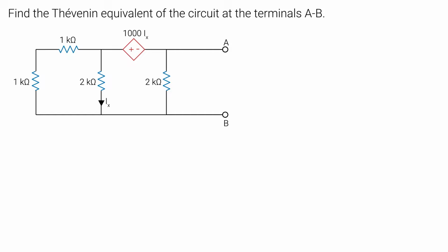Because this circuit only has a single dependent voltage source, there is no way for us to figure out a VOC or RTH since there is actually no current flow in the circuit. But we do need a voltage between points A and B. So instead, what we do is attach a 1 mA current source between terminals A and B.